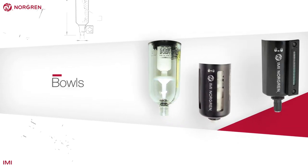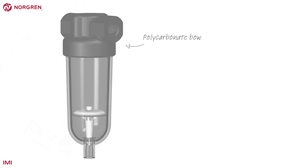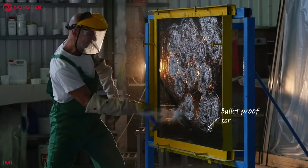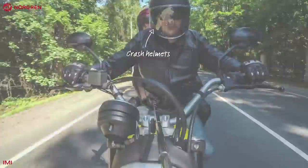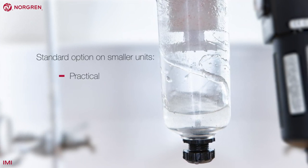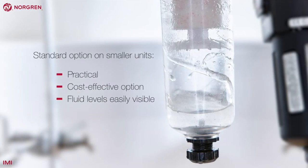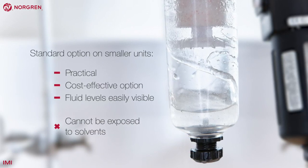Although we have already mentioned them, there are a few important considerations when selecting the bowl. Norgren has 3 types. Polycarbonate bowls can be produced to local standards, but all meet British standards and are very safe if used properly. Both bulletproof screens and crash helmets are made with polycarbonate, so it can be incredibly strong. On smaller units, polycarbonate is the standard option. It's a very practical and cost-effective option, with fluid levels inside easily visible. It does have its limitations, though, and can't be exposed to solvents either internally or externally.